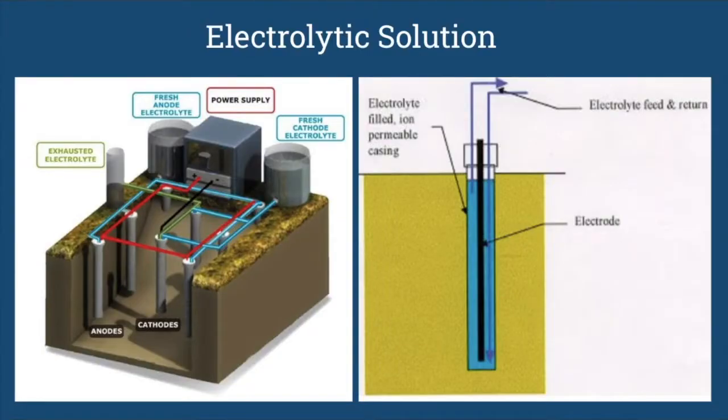When the direct current is applied between the electrodes, the charge on soil, water, and the contaminant will cause migration towards oppositely charged electrodes. In general, active electrodes in water cause an acid front at the anode and a base front at the cathode. The pH will drop at the anode and increase at the cathode.